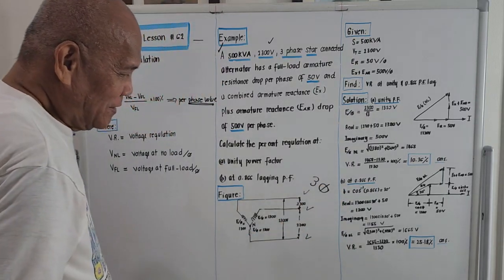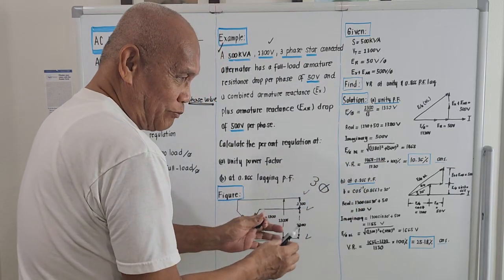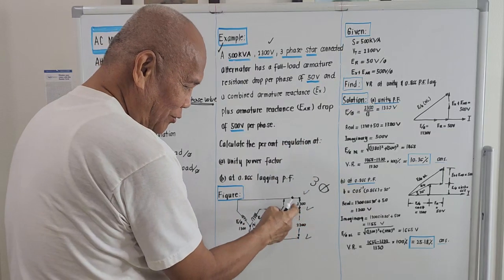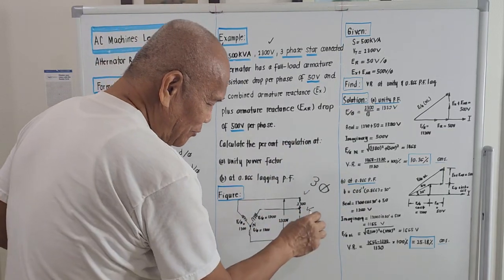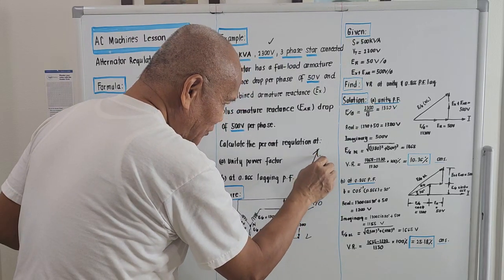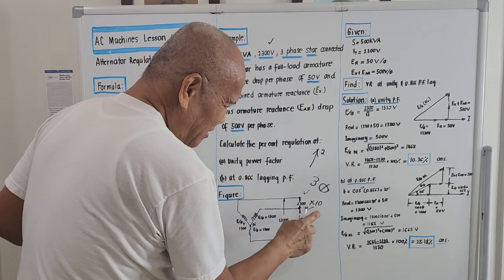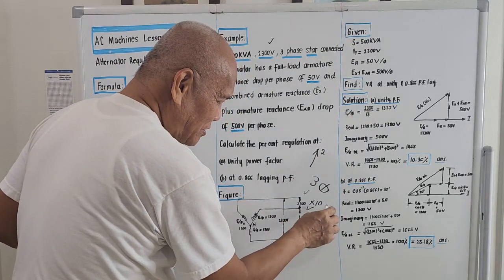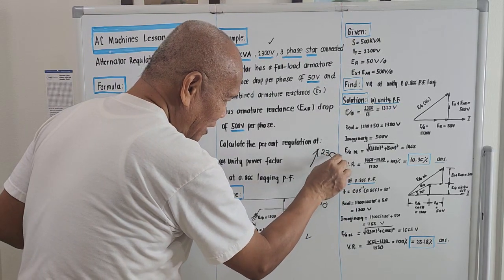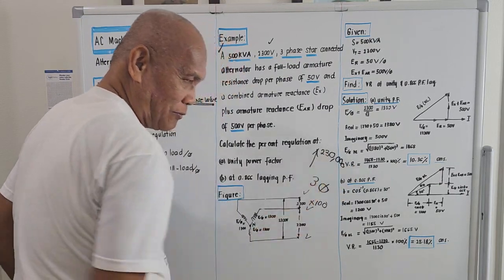So this is the one going up to the transmission line now. But before we feed the transmission line, we should step up the voltage of 2300. We might multiply this by 10 times, or 100 times, so the voltage on the transmission line may be 230,000 volts.